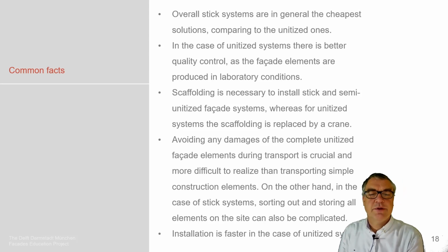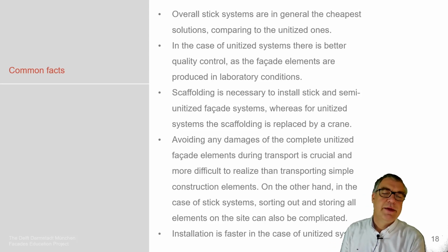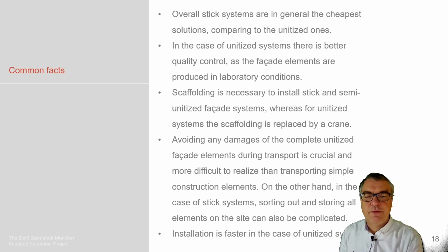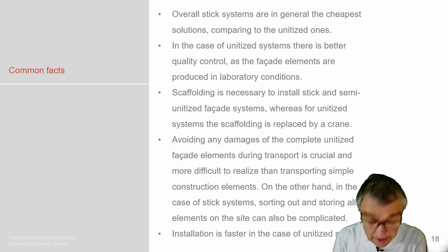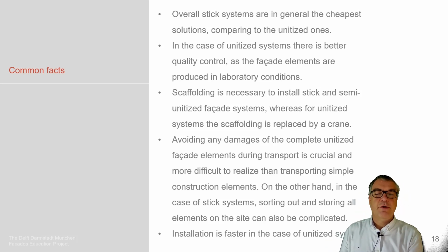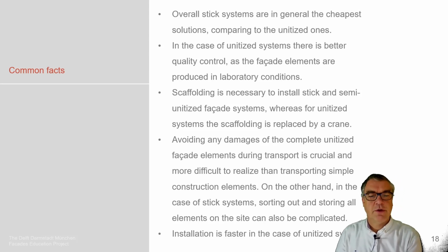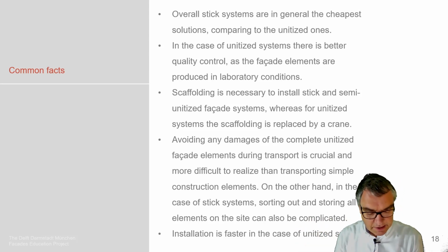And obviously, we have to take care with the unitized system when we transport them to the construction site, that they're not damaged, which can be an issue with stick systems. You obviously can maybe exchange components on site, maybe an easier setup. And obviously no scaffolding with unitized systems. So unitized systems tend to be faster installed because lots of work is done at the factory as a system.